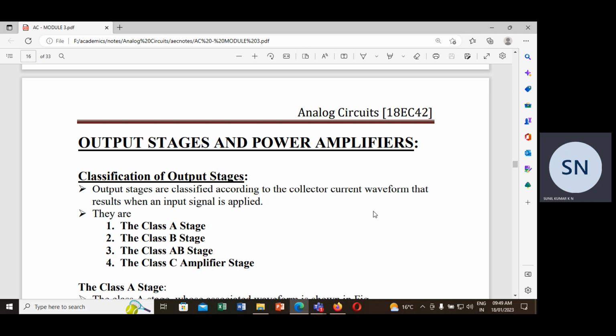This is what type of biasing scheme? Voltage with drain, like collector to base feedback resistor. Here I have already employed output to input negative feedback. So there is no point in employing RE, because the purpose of RE is negative feedback.